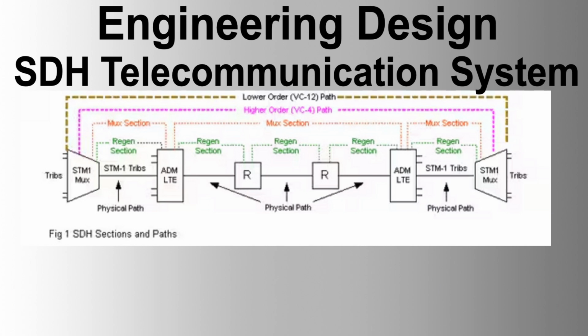The SDH hardware, SDH STM16 terminal. The SDH STM16 terminal shall comprise optical line terminal equipment, OLTs, add-drop multiplexers, ADMs, and other necessary hardware components. OLT specifications. Minimum specifications for OLTs include compliance with ITU-T G.957, launch power, receiver sensitivity, protection requirements, and modular design for maintainability.